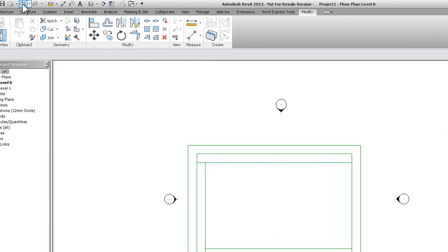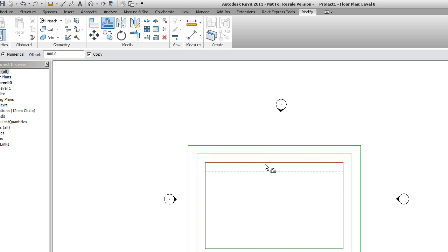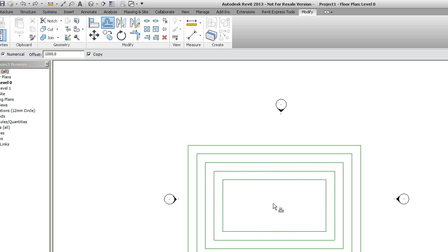What I'm going to do is undo a few stages, to there. This time I'm going to hover over that. Now can you remember this little fella? We're going to hit my tab button. It soft selects everything in the chain and shows you exactly how it's going to offset it. Left click, done. Let's try it on the inside. Hover over it, hit tab, left click, done. Hover over it, hit tab, left click, and again. Quite therapeutic. I'm nodding off. But you get the idea. It is lovely and easy.